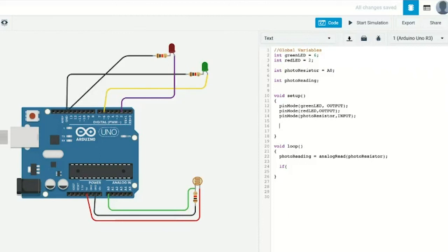We're going to have to initialize a serial connection in our void setup. Let's call Serial and add a period. Then type begin with a lowercase, watching your capitalization on Serial, and pass it the baud rate. This is the speed at which it's going to be sampling from the microcontroller, and that is 9600.